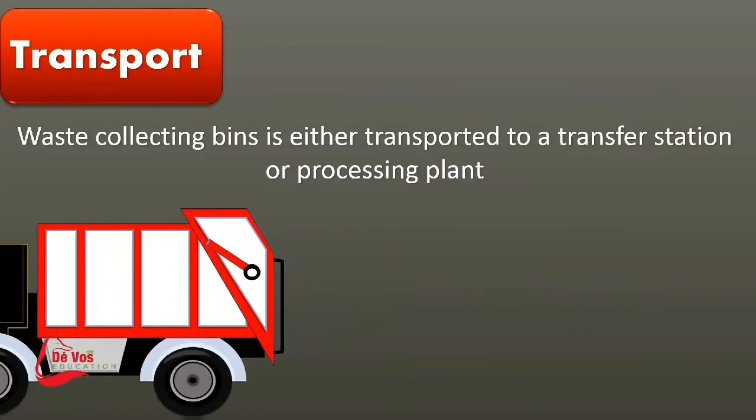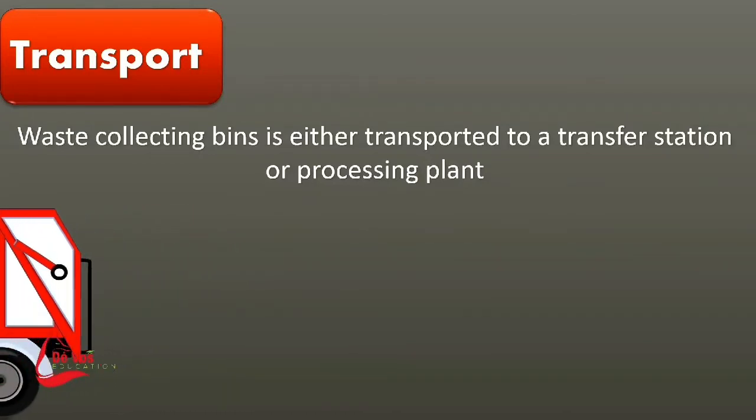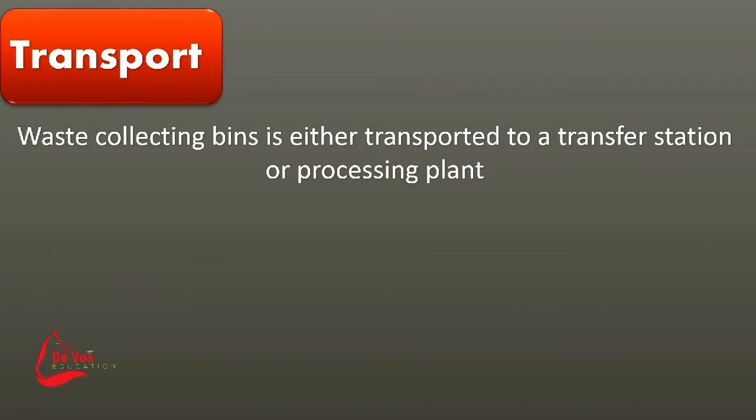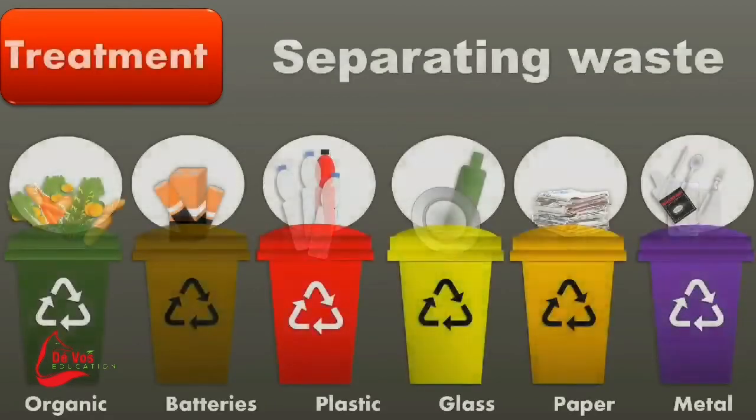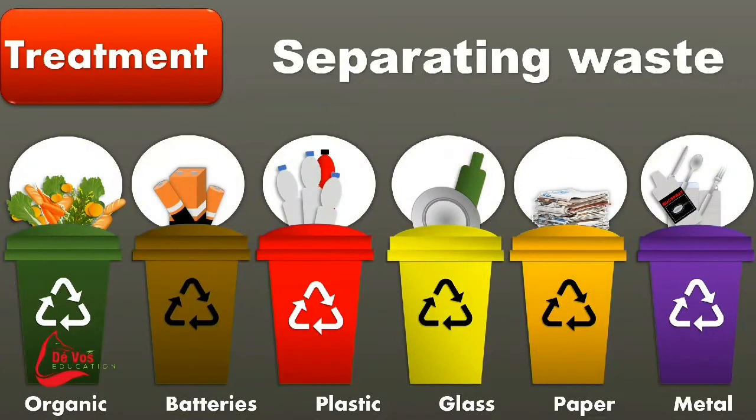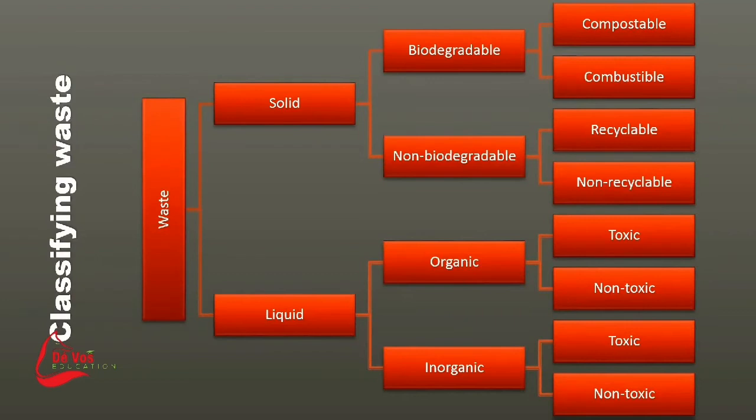When choosing the most suitable vehicle, we need to take into consideration the terrain and the road access conditions, the waste density that has been generated, for example, what is wet waste and what is dry waste. The type of waste, obviously, some might be abrasive and corrosive. The service frequency and the waste generation rates, how often is waste generated, as well as the haul distance to the landfill or to the transfer station, and then the crew size for loading and unloading.